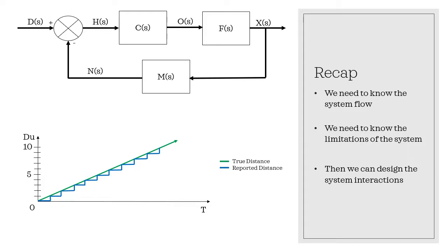So that's basically what I wanted to cover for this lecture, just a reinforcement of the kinds of questions that we need to be asking when we're designing a system and the kinds of things to think about when we're analyzing a system, because everything I just covered applies to every system for the most part in broad strokes. For example, in the temperature controller lab that we did, our granularity of input was 1024. We could read 1024 different values of temperature. And was that enough to control our system, keep it within the range? It was in this case, but what if we needed a very precise range? What if we're doing a very delicate chemical interaction and we need to keep that reaction chamber at exactly the correct temperature? Would 1024 values be enough?